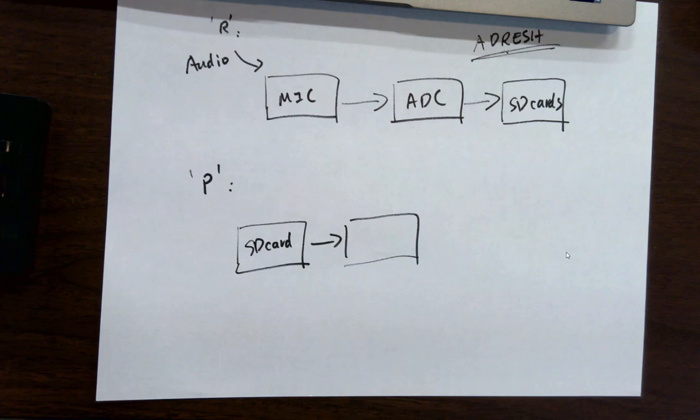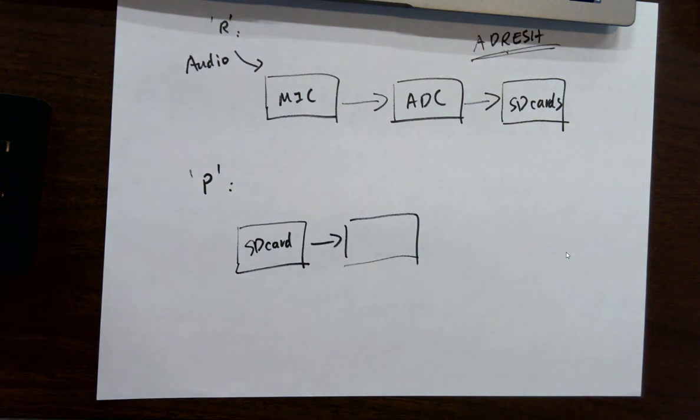These are bytes, right? So which module do you want to use to send it out from the microcontroller? Bytes are digital signals. These are like 8 bits. How do you convert 8 bits into an analog signal for the speaker? Because the speaker is only receiving analog signal, then play, right? It's an analog signal being played, getting to the audio amplifier and then the speaker, right? So before that audio amplifier and speaker, and after the SD card, what's in the middle? What's connecting the two? PWM.